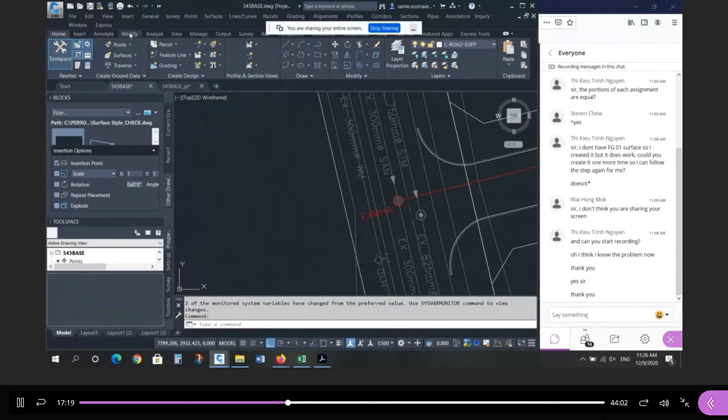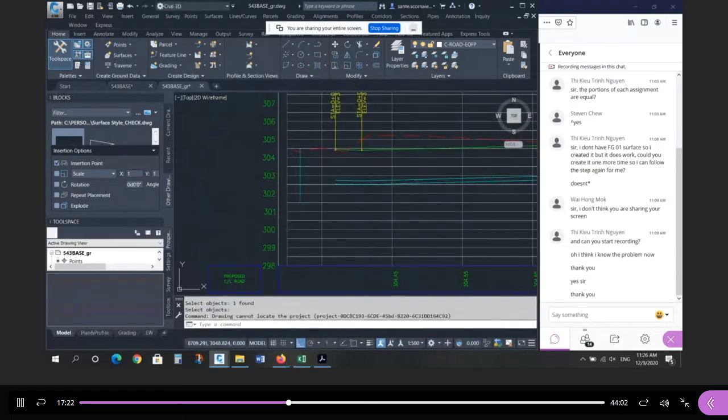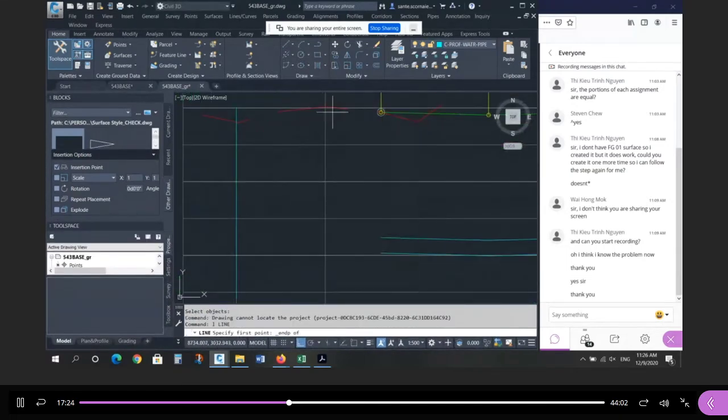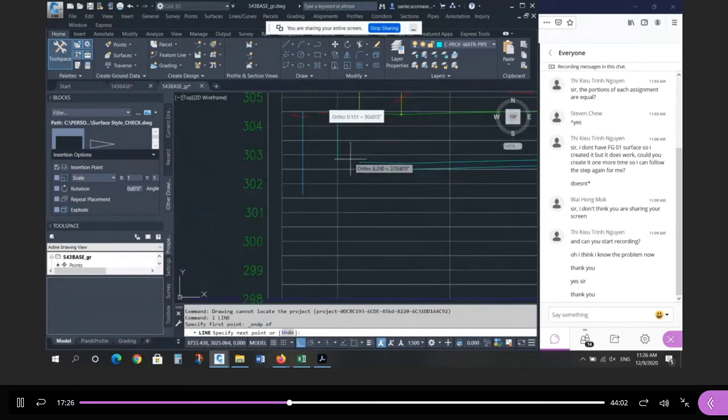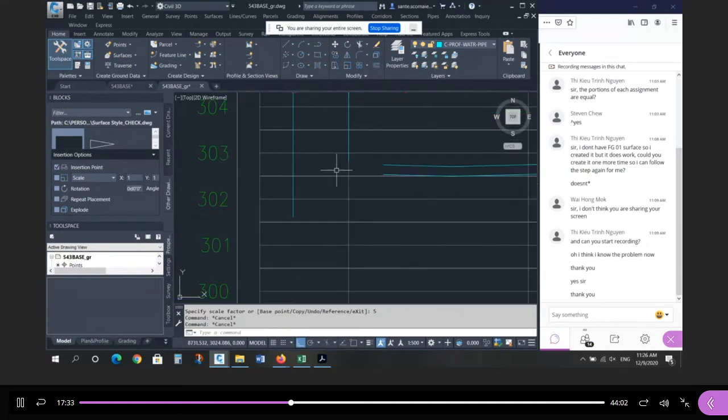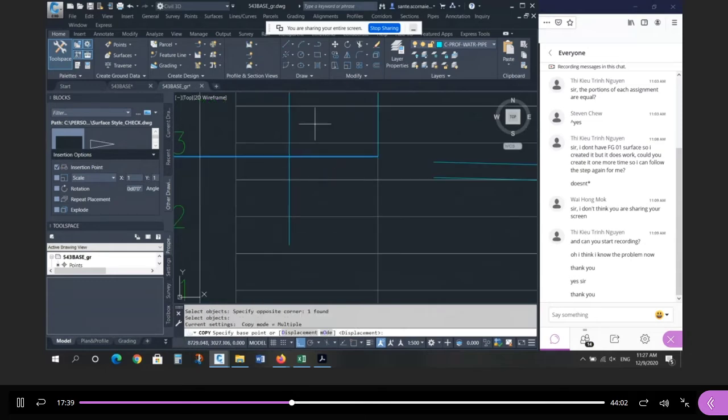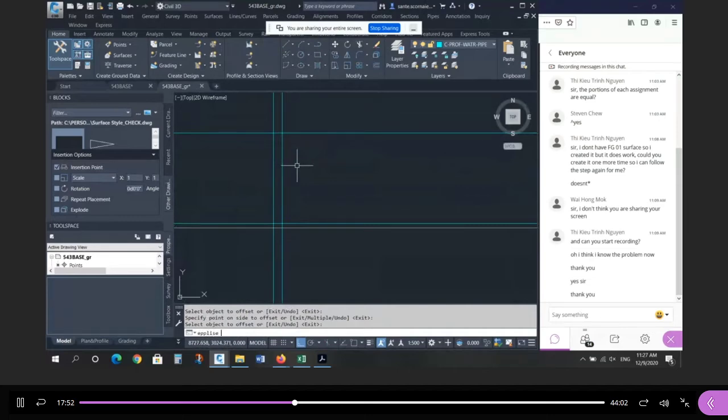So we want to draw an ellipse with a 300 diameter, right? And I'm going to assume it's below the center line of road by 1.7, but I have to multiply that by 5. So I'm going to scale it by 5. There's the top of the water main here. And across here, that's the top of the water main. Make a copy of that straight down. 0.3 times 5, which is 1.5. There's the bottom of the water main, and then I can offset it half of 0.3, 0.15. I don't need to exaggerate that in the horizontal. And then I can draw the ellipse.